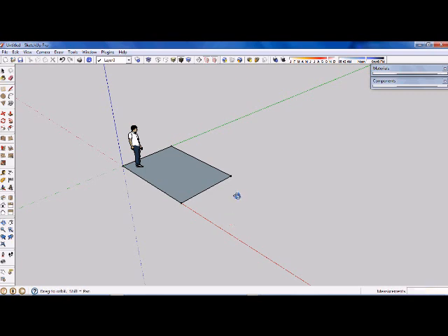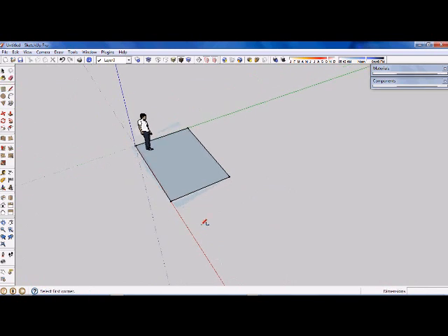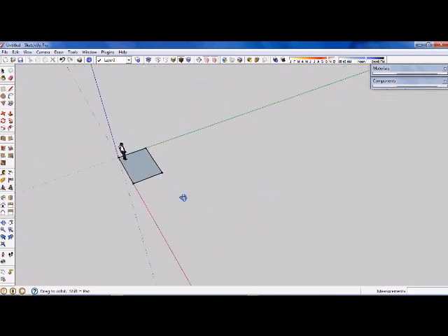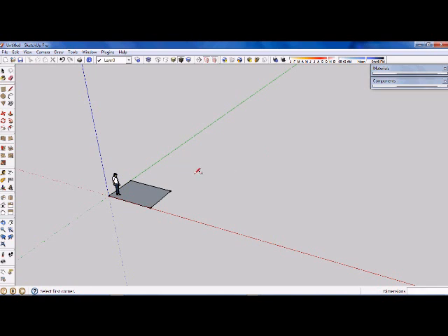Let me do that again, showing you that second option that I showed you earlier. I'll click another rectangle out here somewhere. I'll sketch a shape roughly what I think I want the dimensions to be, and then after I've clicked there, what I really wanted it to be was something like 4200, 1200, and then press enter. And that resized the last rectangle I did to those dimensions.